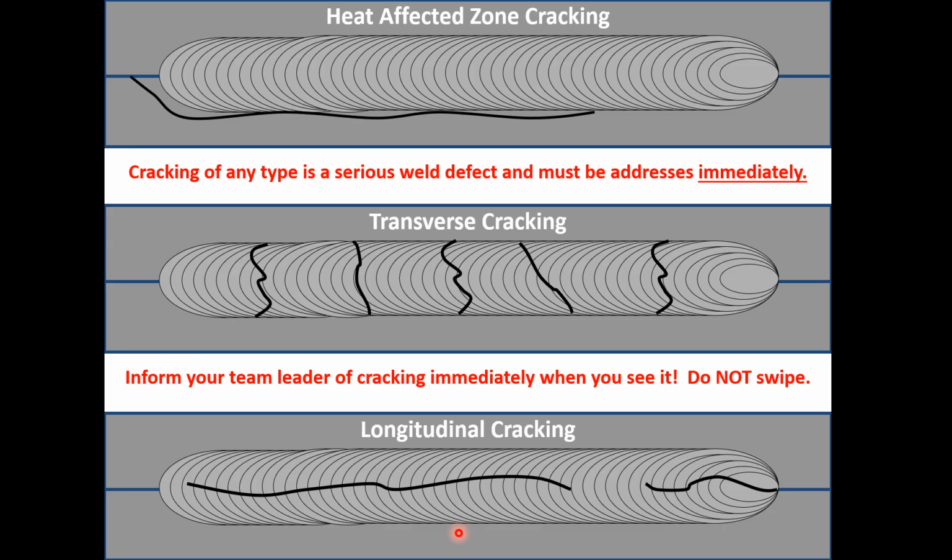And when it starts to cool, then it starts to shrink. And if it shrinks too much, if the weld's too heavy and it's too thick or whatever, it'll start pulling, and it'll actually pull itself apart. It'll pull itself apart in the last spot to cool down, right down the center of the weld, right? Because the base metals themselves are pulling the heat out.